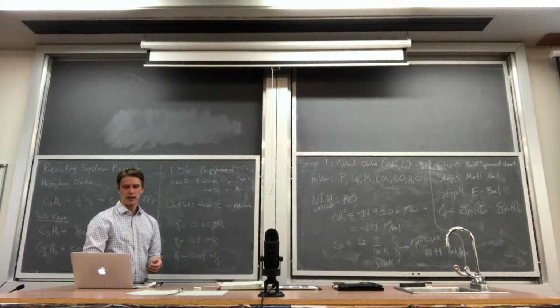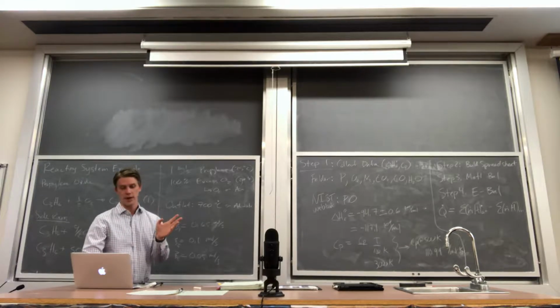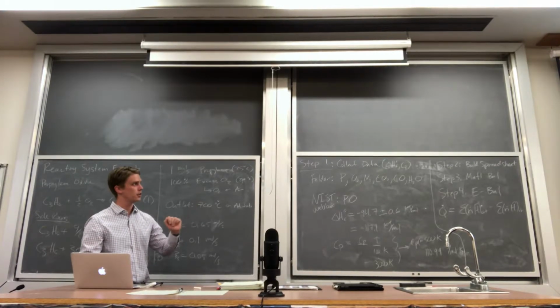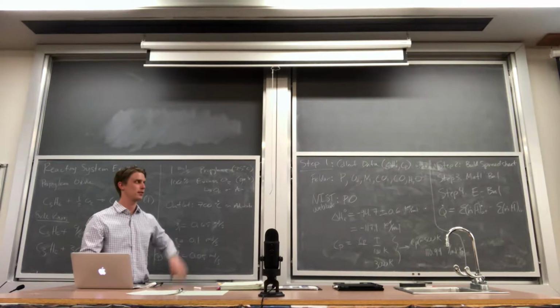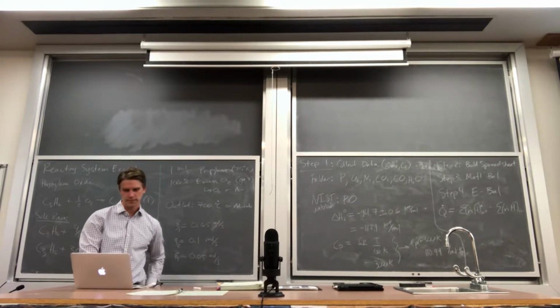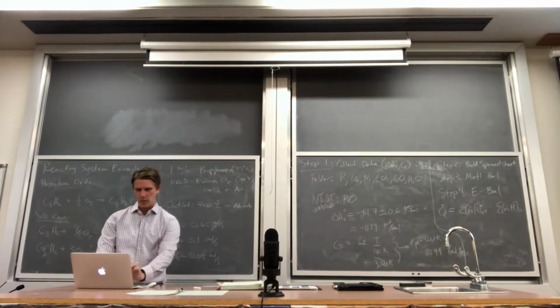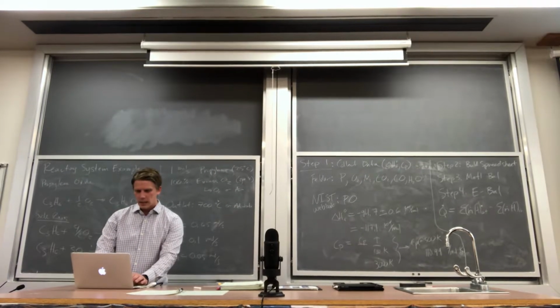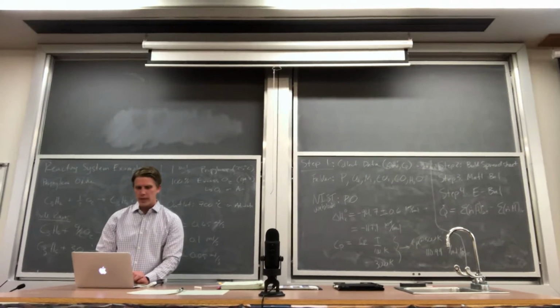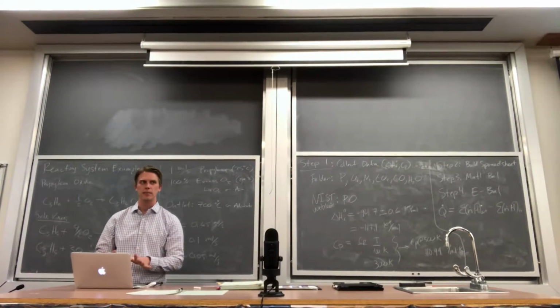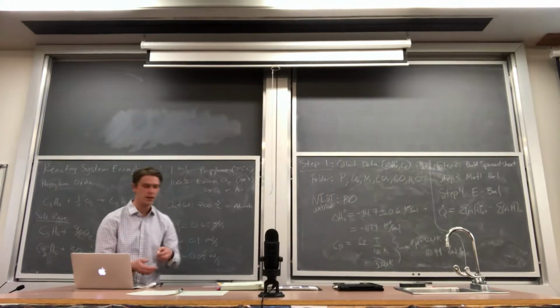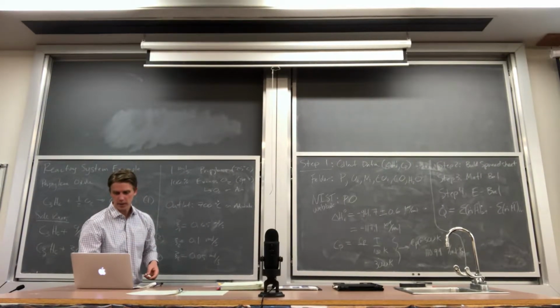Everything is coming in, well, 2 things, right? You have 25 for the propylene, and then for the oxygen is 200, and then I just put 0 because there's nothing of those other things. So, now we get into the meat of the problem. Our enthalpy coming into the system following the heat of reaction method is given by this big, long, unfortunate equation.